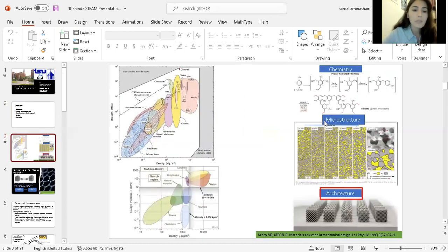Let us look at some material properties charts here. For example, strength with density or Young modulus with density, we can see that metal occupy the top right hand side corner as expected. The foam occupy the bottom left hand side, and in between we see the polymers, composites and so on. The lattice structure have great potential to occupy the unfilled area, such as the top left-hand area.